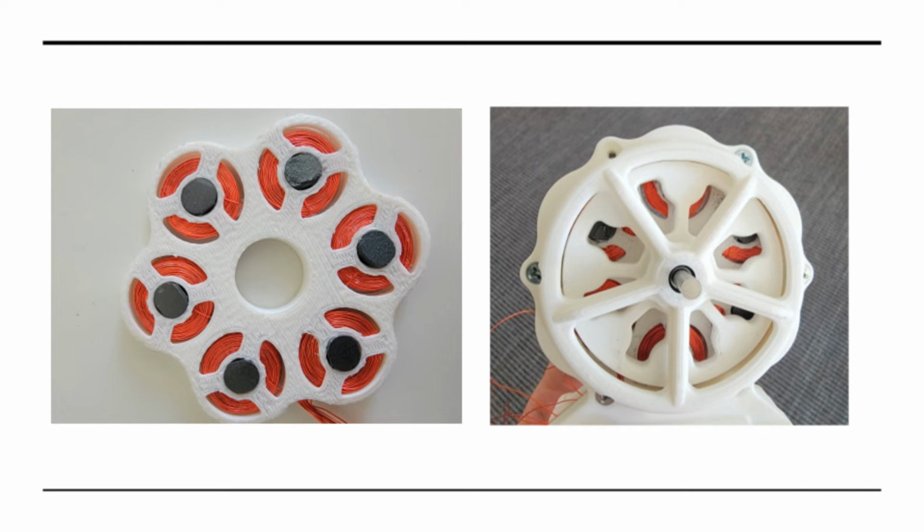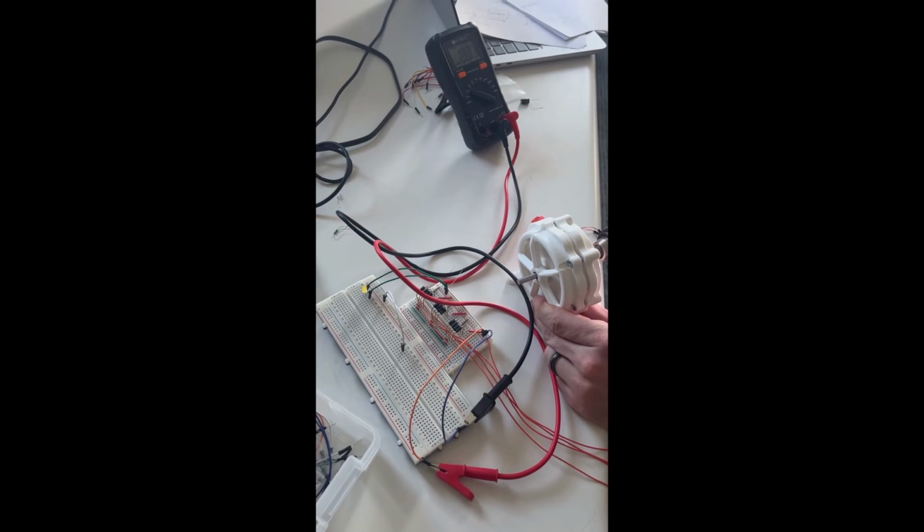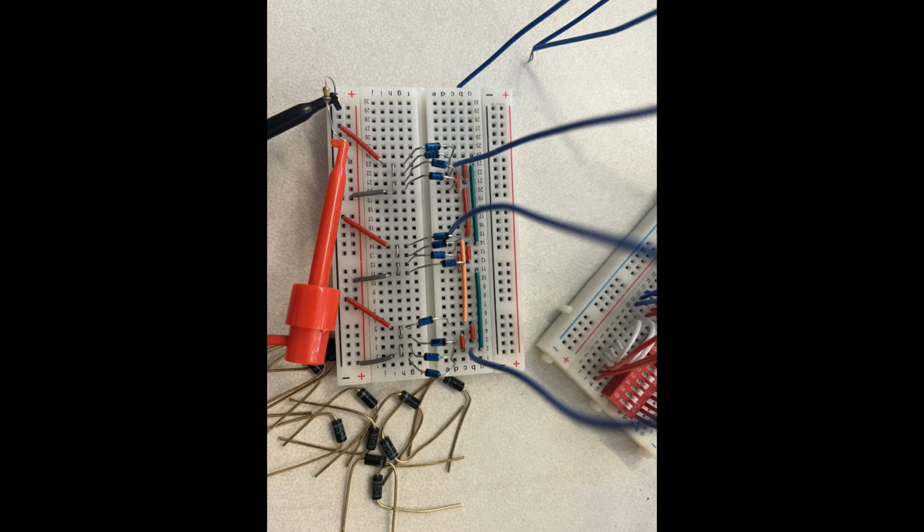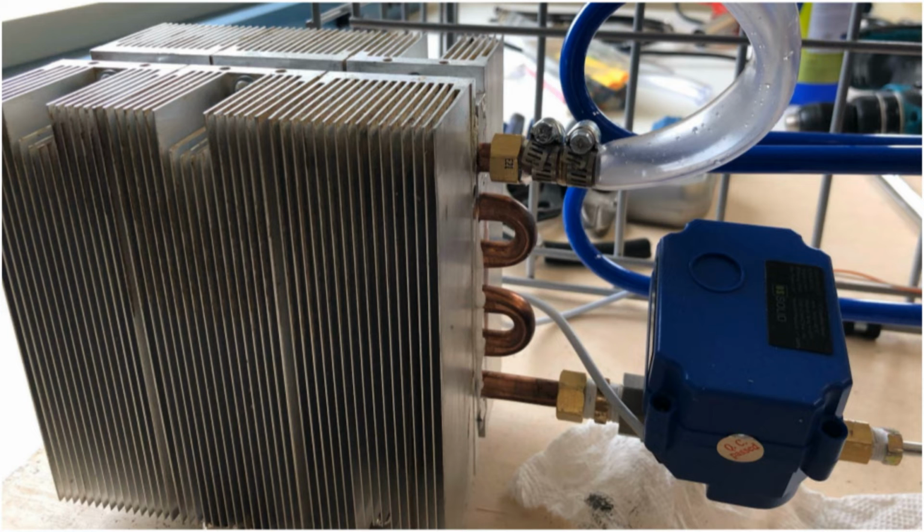For electrical generation, the self-made axial flow generator is capable of producing a testable 4.5 volts. The generator consists of 3 phases, which uses 2 coils per phase. The circuit functions using 3 full bridge rectifiers with a Zener regulator circuit to convert AC to a usable stable DC voltage. The fluid is stored in a reservoir and then cooled down in a radiator with aluminum fins.